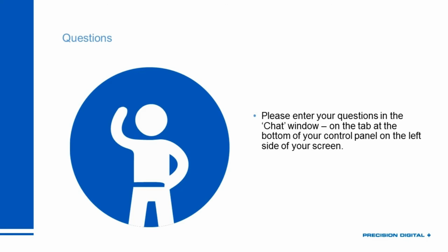Joe? Actually, if I may make one comment based on a couple of input that we've had into the chat window. A few people have asked, based on what I just said, shouldn't you only ground one end in order to prevent ground loops, etc.? They're absolutely right. You only want to ground one end of the cable.